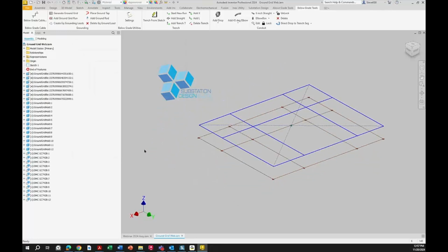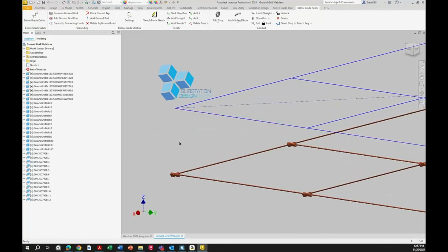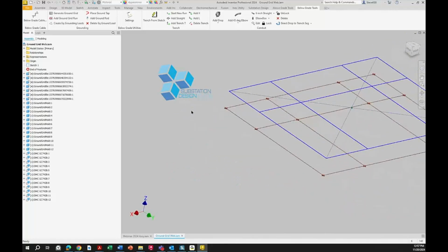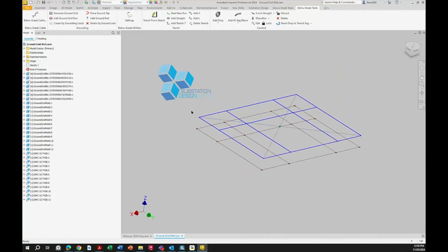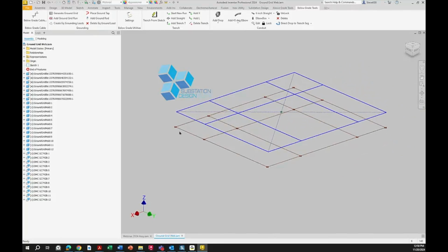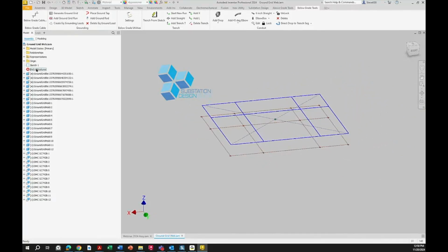So what I got now, I told it to build it below the depth of grid. So my grids, I tend to put it on the XY plane just out of habit. It's my reference plane, top of concrete type of thing. And I'm going to build it below there. So I built it below. I don't need to see the sketch anymore.